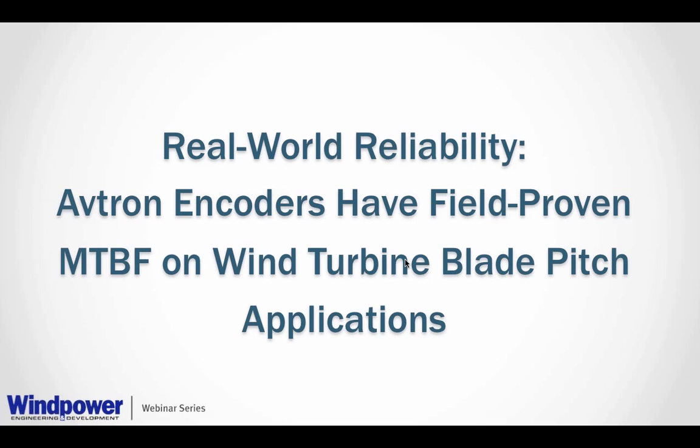So if you look at real-world MTBF, Avtron actually has tens of thousands of these units on blade pitch units all over the world. We've got units on generators and so on. And Avtron has measured our MTBF, our mean time between failures, and we have a 4.5 million hour MTBF on blade pitch applications. You say it's crazy. You do the math, figure it out, it's 500, 400 and some years. That can't possibly be true. We're not talking about how long the encoder lasts. We're talking about how few fail. How do we get there?